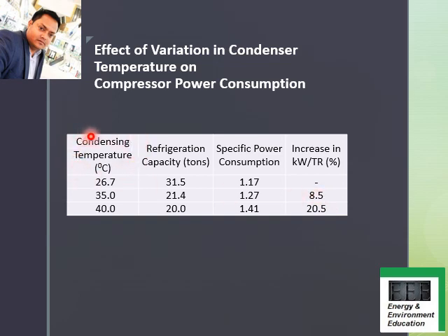So unlike the last slide where the evaporator temperature was kept as high as possible, here in the case of condensing temperature, or you can say in the case of the condenser, you have to keep the temperature as low as possible, friends. This is also a very important concept. So you may expect to have some questions based on these two concepts. The last slide that I discussed, and this slide also, is very important for you to understand as far as the exam is concerned, friends.